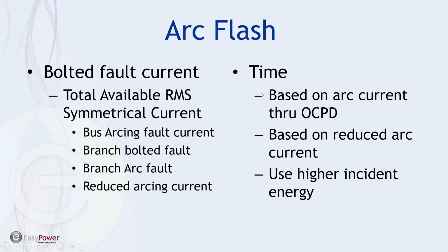Another element that's affected by these manipulations is the time, and the recognition that the current in a shorted fault or an arcing fault can change over time and affect the trip time or response time of overcurrent protective devices. So some of that gives us pause as far as how and whether or not it's even affecting our calculations and how we deal with that.